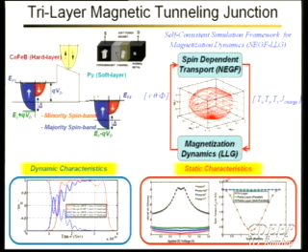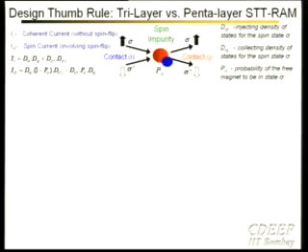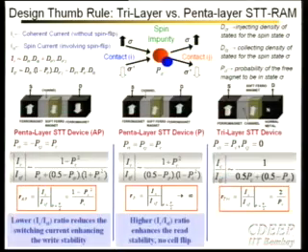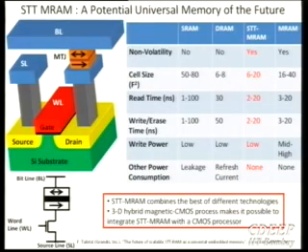But the interesting thing to note is that if I have the right kind of MTJ structure, I can have two different resistances depending on whether it's anti-parallel or parallel. I'm going to skip this. It turns out some tri-layer junctions are actually good, but you can possibly get a better difference in the resistance if I were to have pentalayers. Of course, the fabrication of pentalayers is going to be a little more difficult than the tri-layers. And we've been looking at some of those, but the pentalayers give you better memories.